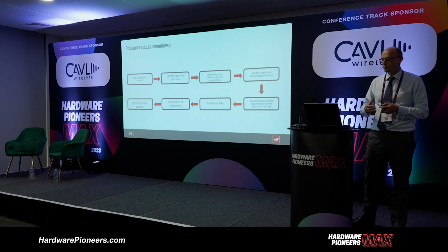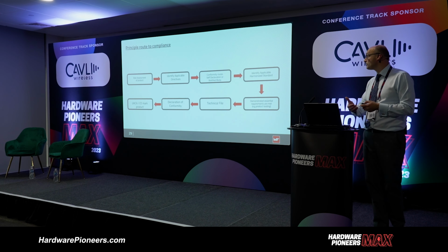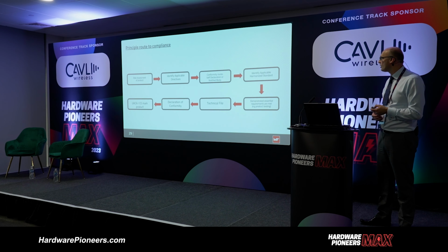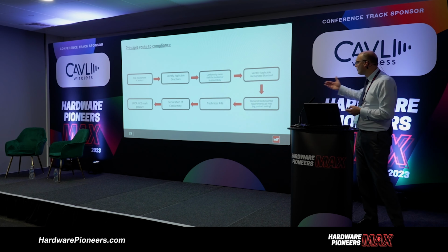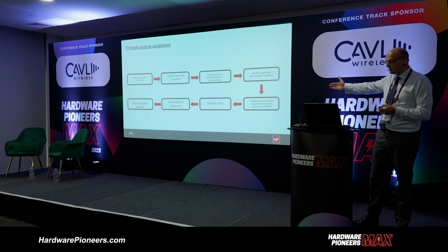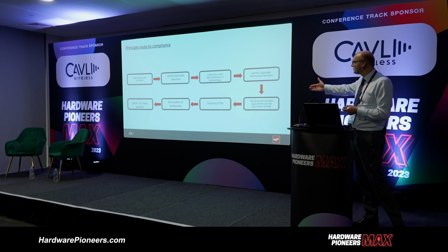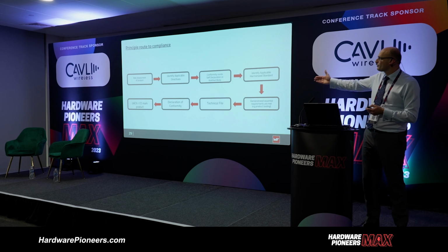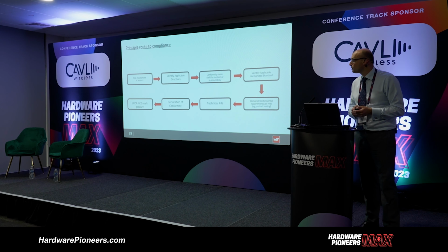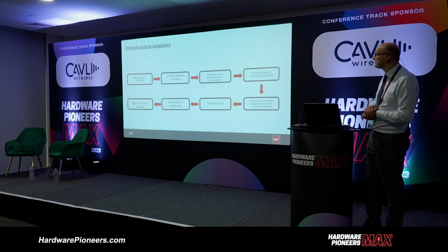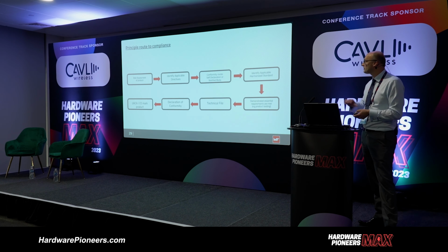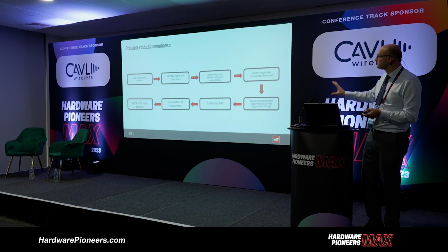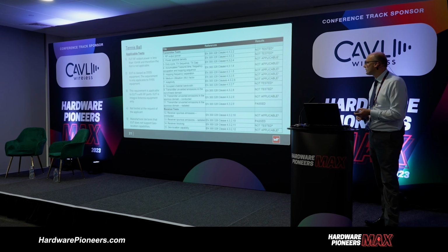Once again, very helpful, I've been able to use the pre-approved module from Wurth Elektronik as our harmonized standard route. We've then done additional testing to make sure we can still meet some of those essential requirements. We've documented that in our technical file. From that, we can then issue our declaration of conformity, and I can then place a UKCA mark or CE mark, once again subject to what market we're placing the product into. So that's the plan of action.